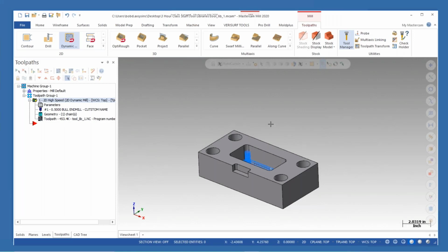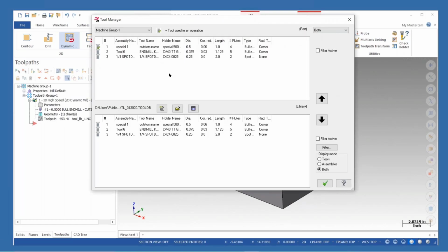The tooling cloud, again, is something that you can go on Google and search, and it's a fairly fast download, and there are literally thousands of tools and holders. So if you know something specific, if you have a job coming up, you can go into the tooling cloud, define your job, put all the tools you need for that job in there, import them to Mastercam, and when you start that job, right click and say import tools, import all of those tools, and now you're ready to go. Make some fine adjustments to speeds and feeds, grab those and put them in your tool library.